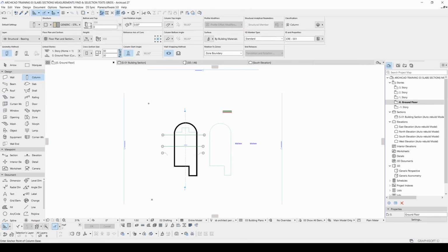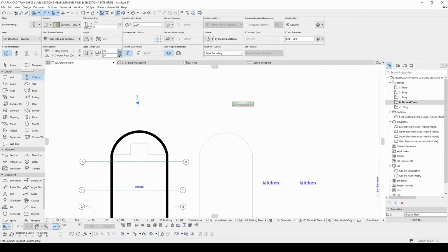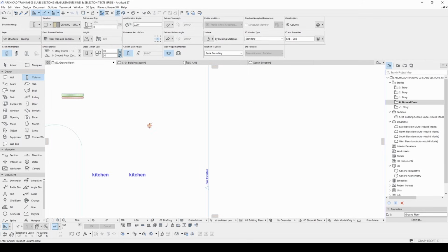When we click the column tool, you will see more options, and actually each option is the same as the others. So you can change your starting elevation and elevation, you can change its direction or edit them after, or you can change its settings. For instance, as you can see, for the geometry method, we have selected simple, or you can make it 2 clicks or rotated. They're very simple. First, if you click simple, if you click here, it will immediately create your column.